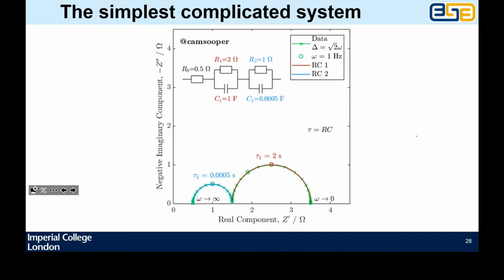So high frequency, if you want to go forward and then back and then forward and then back, this elastic membrane, well, it doesn't care. You're deforming it so little before you start going back in the other direction again. It's as if it wasn't there at all. So with a capacitor, and as you'll notice from the Nyquist plot, as frequency goes to infinity, the impedance goes to 0. So if you want to push things backwards and forwards through a capacitor, it's as if it's not there. It may as well just be a wire.